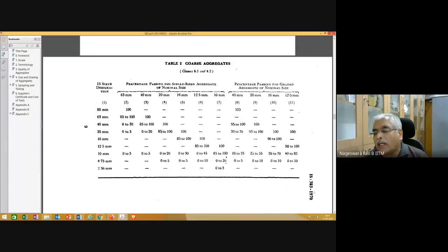So density of concrete is going to depend on the overall density of all these aggregates, cement, and other things. Density of concrete has nothing to do with the size of the aggregate. With the size of the aggregate, we are making sure different sizes are available there, so that packing is proper.